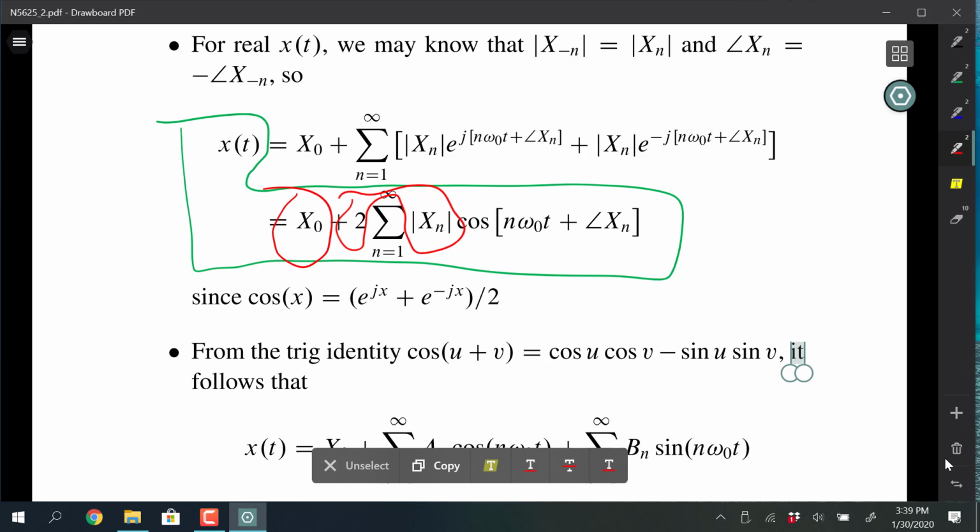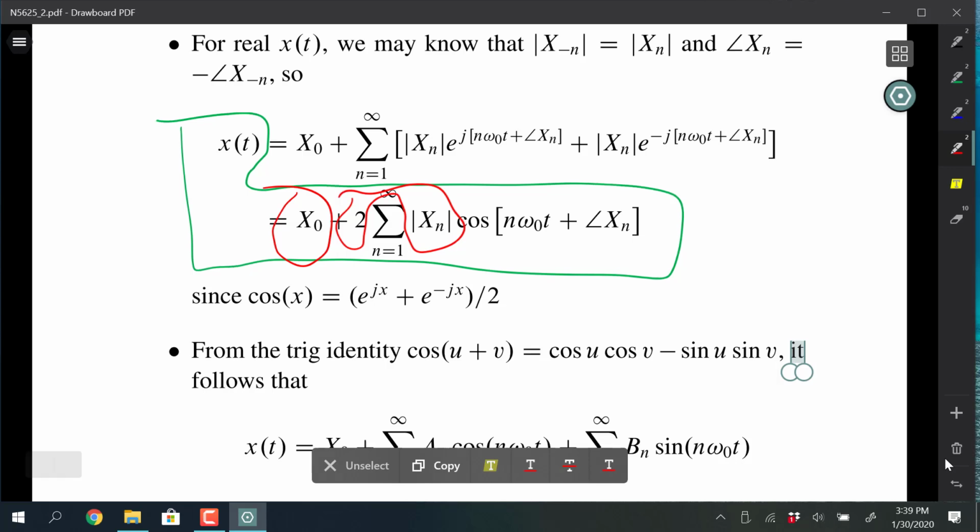So in my mind, when you're doing a one-sided spectra, which is what the spectrum analyzer displays in the lab, you're actually working with this form of the Fourier series. And it's not really bizarre at all, is it? It seems very natural. You have a magnitude and a phase associated with the positive Fourier coefficients. And I have a line spectra plotting function in my Python module SIGSYS, so it plots line spectra and uses that information.